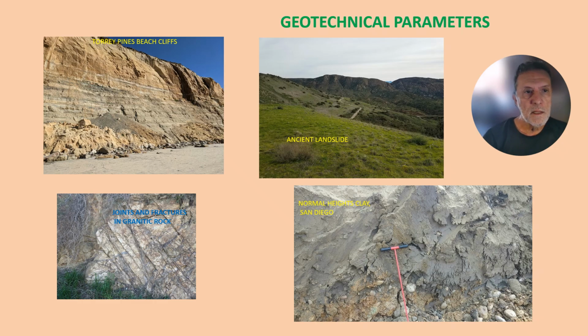So looking at this slide, upper left, Torrey Pines beach cliffs, that's exposed bedrock, of course, sandstone and shale, two very different rock types deposited under different environments during the Eocene. The sandstone in a higher energy seashore wave environment, the shale or mudstone deposited in quieter lagoonal type waters. Because these rocks were deposited under different environmental circumstances in different energy regimes, their properties are quite different.